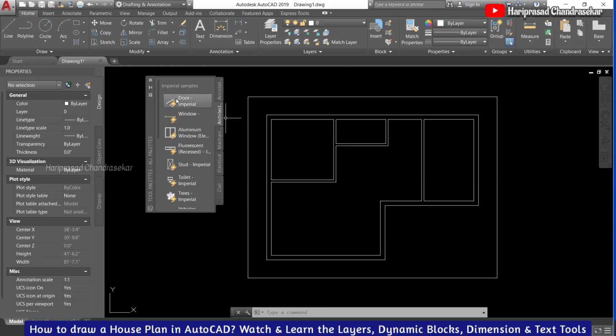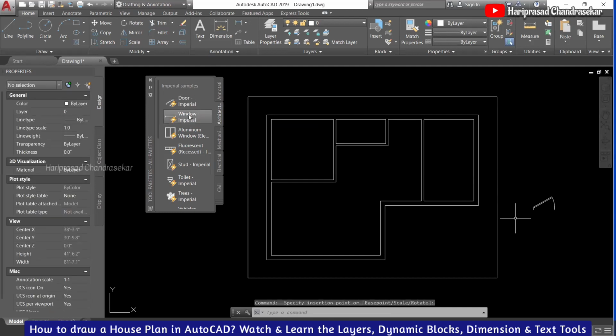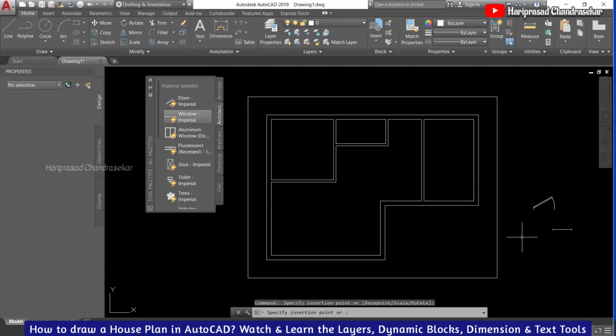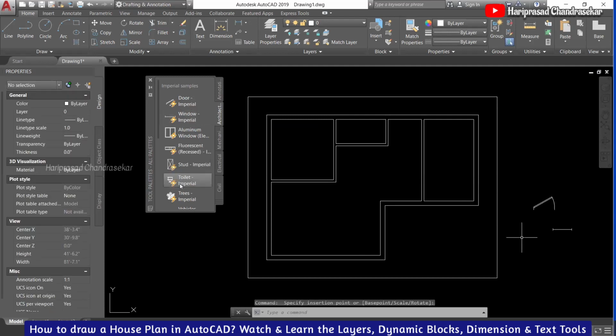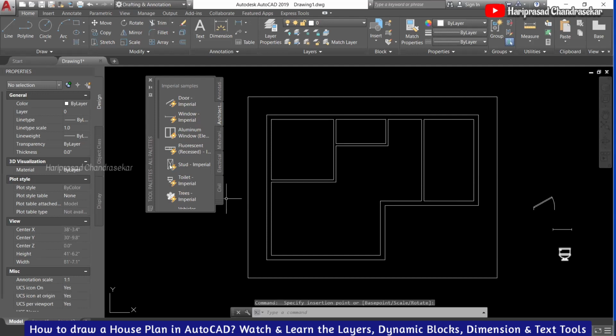So in this tool palette, you will automatically get dynamic blocks. These are all the dynamic blocks in the architectural palette. You can just take the imperial door and the imperial window, and we also have the elevations for those. Also, we can see the toilet. With these, we can have multiple things with the same block. That is what is called a dynamic block.